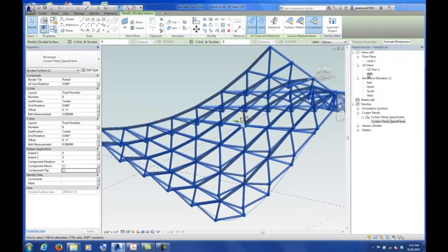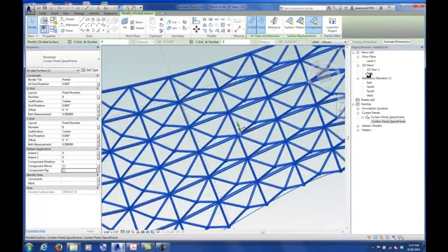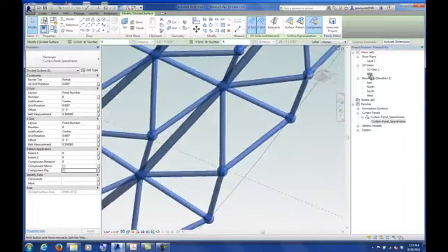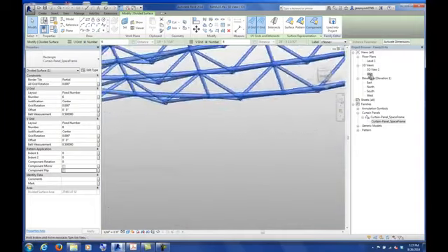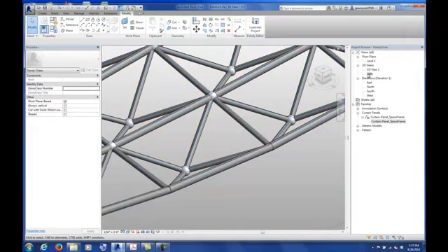Okay. So let's just expand a little bit more on reporting parameters as it relates to this curtain panel. The reason I'm doing that is, remember I did the reporting parameter for the pipe so that my pipe radius is going to change based on the overall length. But right now we have to hard code in the size of the sphere. So I'm never going to know how big the pipe is until it's placed, and then I have to individually each time change my sphere radius to look appropriate as well.